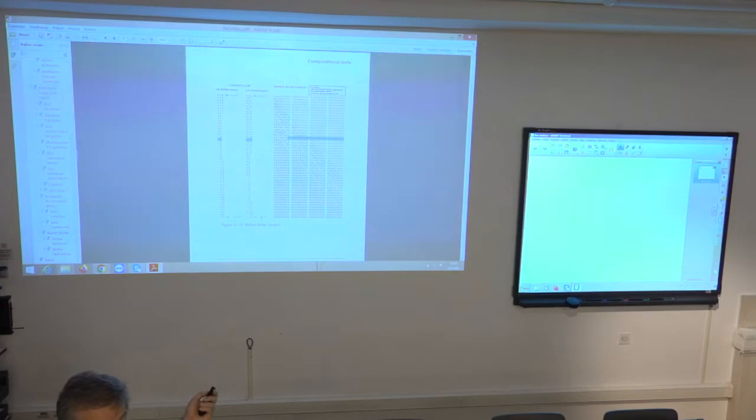You simply write 50 into this register, and it will shift out this value to a position that is not registered, let's say. The value in the final register will be 0. So in that case, you don't have to handle this as a special case. If this shift is larger than 32 or less than minus 32, the result is 0. You simply put in the value of 50, and what happens is exactly what you desire.